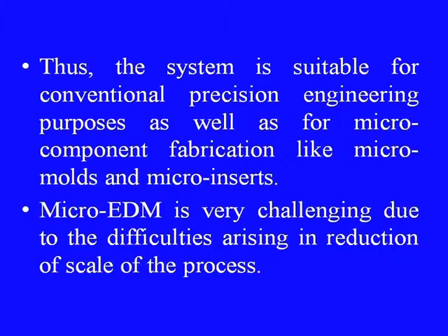Micro EDM is very challenging due to the difficulties arising in the reduction of scale of the process. Fabrication of small electrodes having a small inter-electrode gap, achieving accuracy, removal of debris, and keeping the HAZ, or heat affected zone, to a minimum are very challenging issues in micro EDM.